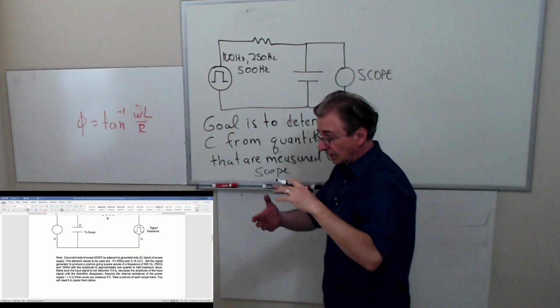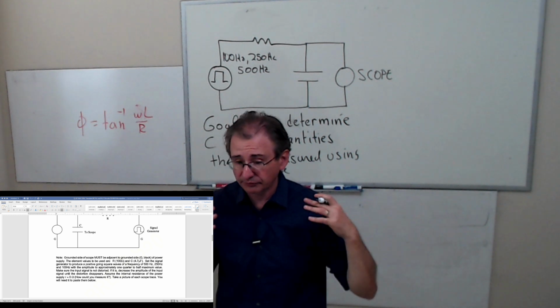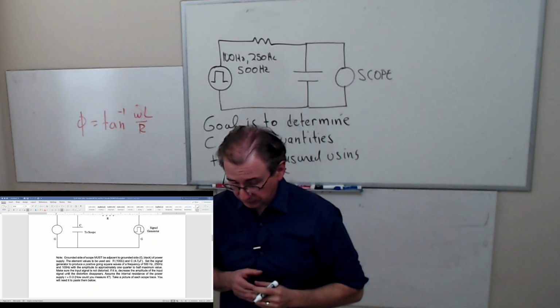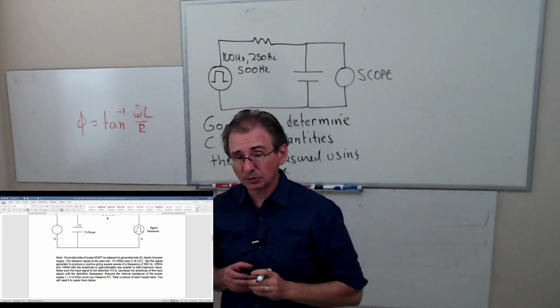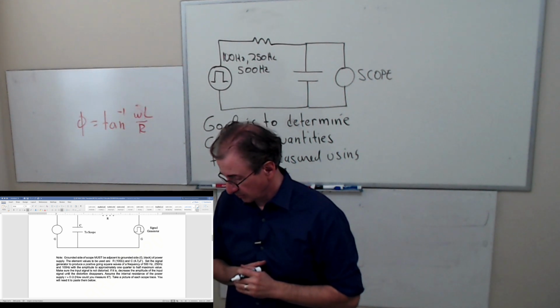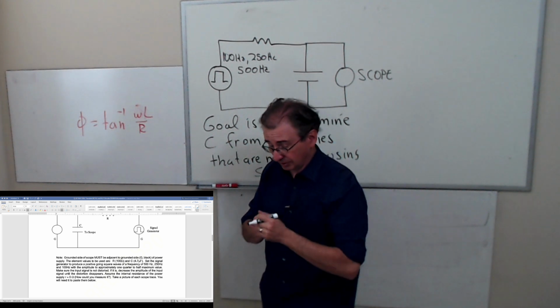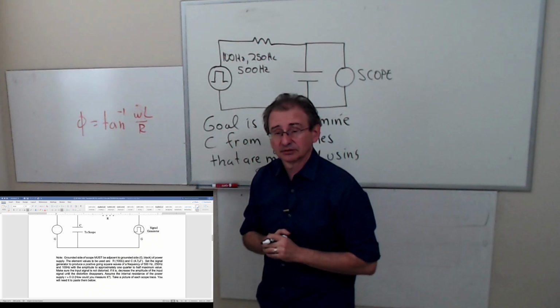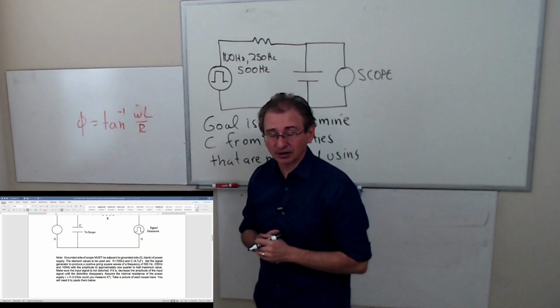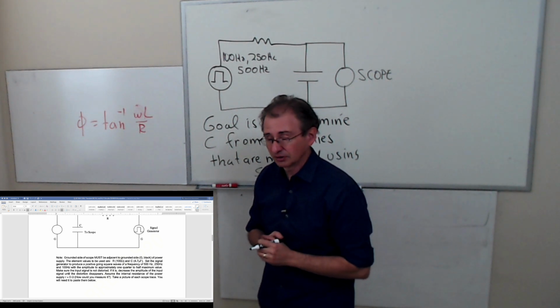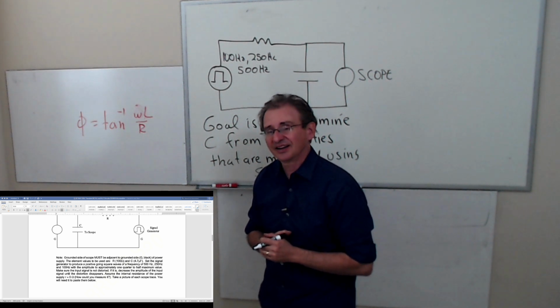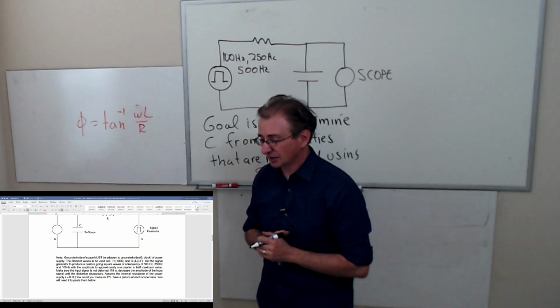So you will be using that little signal generator that you used for doing the oscilloscope quiz. You're just going to set the signal generator for a square pulse. It's kind of cool though. The signal generator can do square pulse, sawtooth, all kinds of interesting signals, and it even does the EKG.